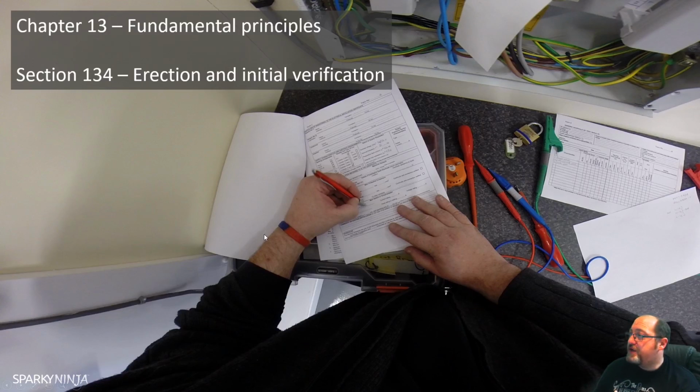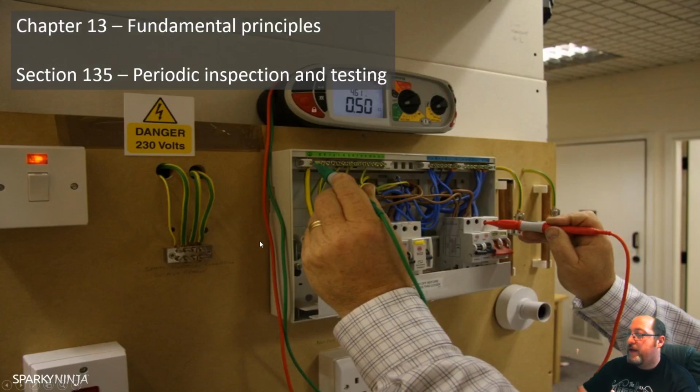Then there's periodic inspection, to finish, 135. It is recommended that every installation is subjected to periodic inspection and testing in accordance with Chapter 65. So it's a recommendation. The requirement for maintenance in the legislation is in Electricity at Work Regulation 4.2, which tells the employer to ensure effective maintenance to avoid danger. Fundamentally, that kind of goes in full circle, and the recommendation is periodic inspection and testing. But you haven't got to do it, it's a recommendation. And that's where we're at.